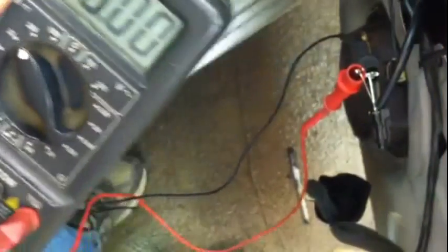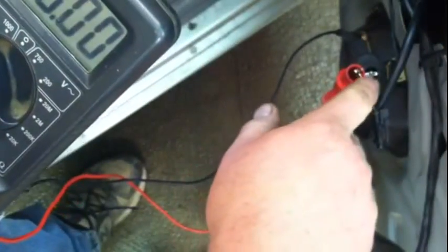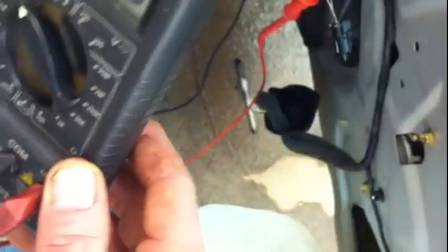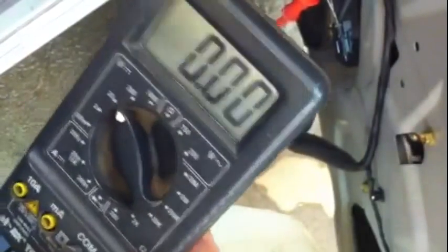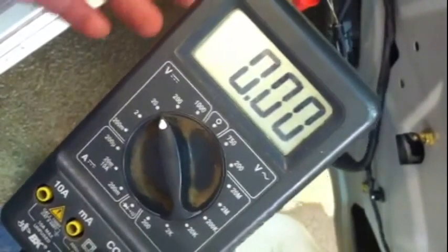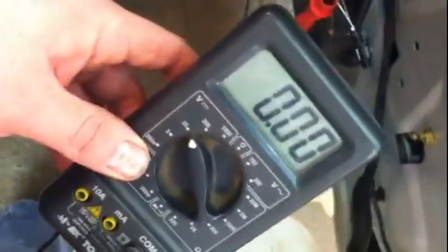Alright everyone, we're back at the car here. What you see here is I have the actual plug for the motor back probed. I can't back probe it out there because it's buried in that hole, so I can't show it to you. But this is another mistake that people make when trying to do a voltage test, or just any type of component test. Now what you're looking for is when you push the switch, you're looking for it to change states. And like I said before, it reverses polarity on the motor, and that's how you get the direction.